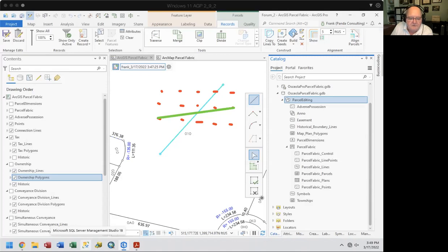So what happens though, when you tell it to go and split that line here, is it goes and finds the ends of those lines and snaps them to the closest point. So that might snap here, this might snap here. And again, this is 3/1000ths of a foot. And depending upon where your edit is, where your divide is, it winds up snapping it to these other places.